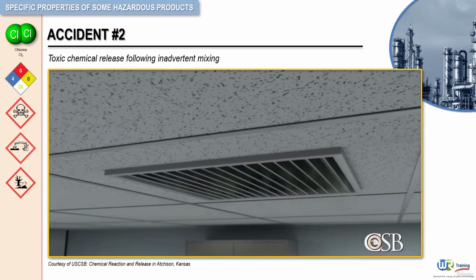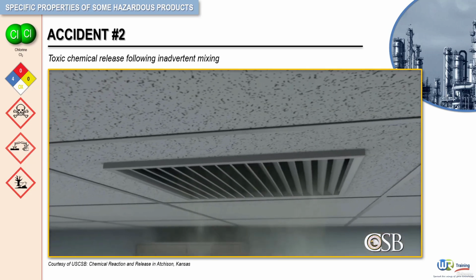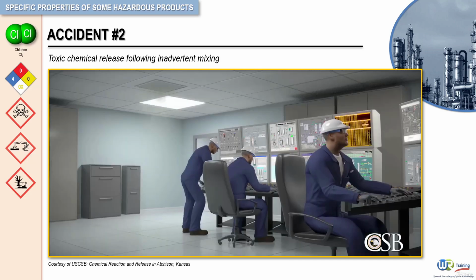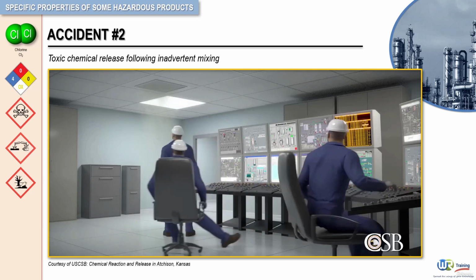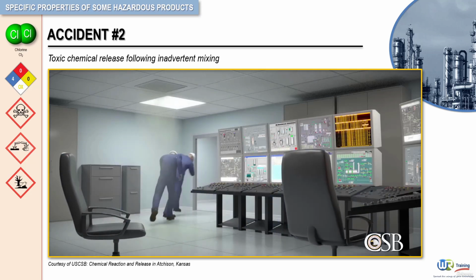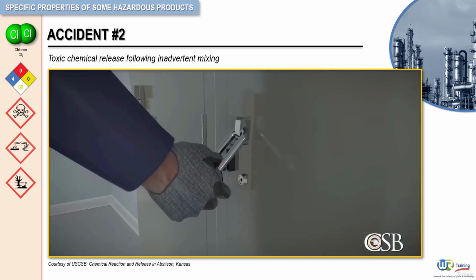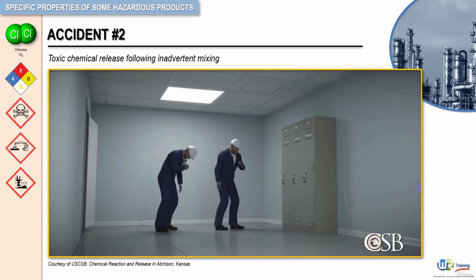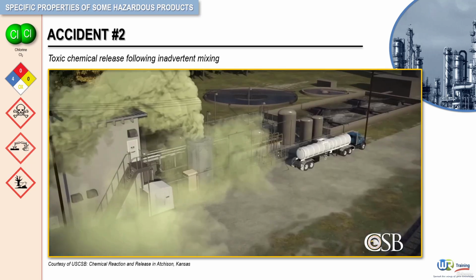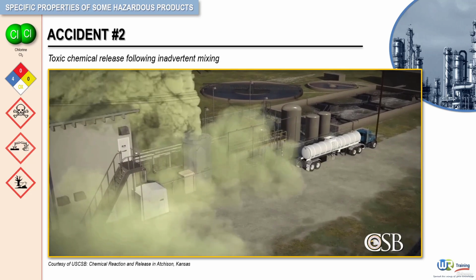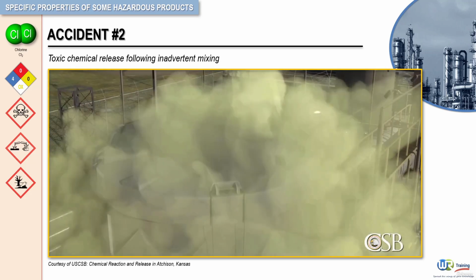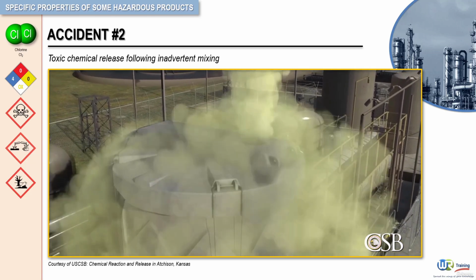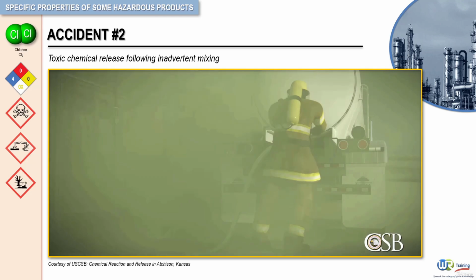At about the same time, toxic gases entered the facility control room through the building's ventilation system. MGPI operators preparing for shift change in the control room were immediately overcome by the toxic gas. Because the operators had a practice of locking respirators between shifts, some were unable to access their respirators before evacuating the building. With no other way to stop the flow other than closing manual valves on the fill line or truck, or by triggering one of the truck's emergency shutoffs, the sulfuric acid continued to enter the sodium hypochlorite tank for nearly 45 minutes until emergency responders shut down the flow.